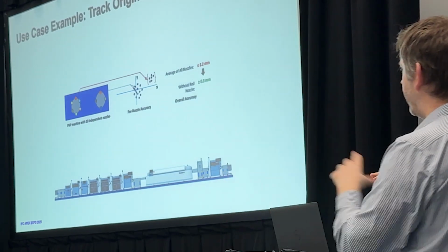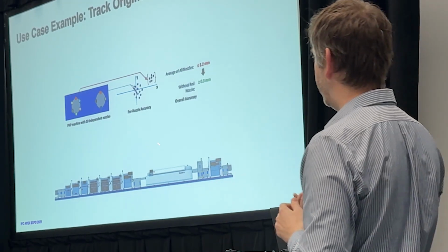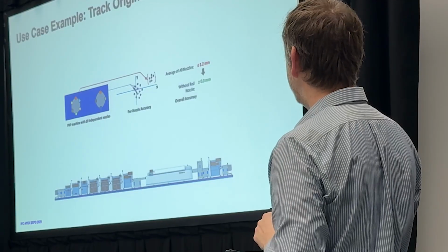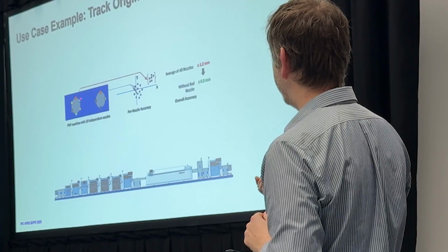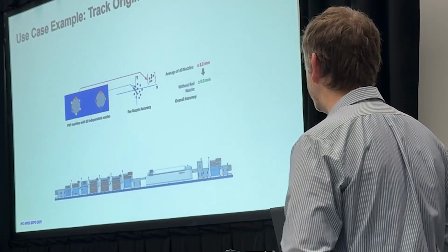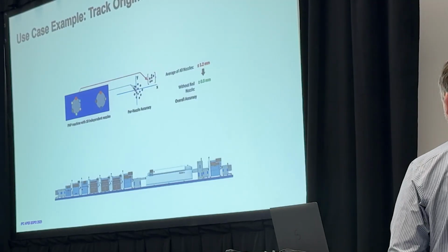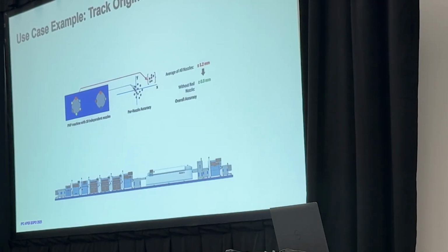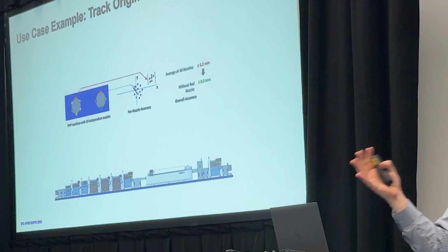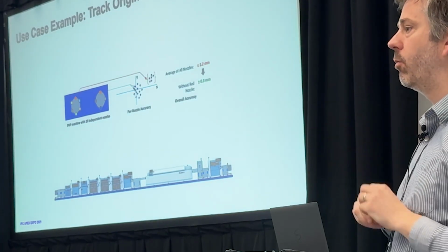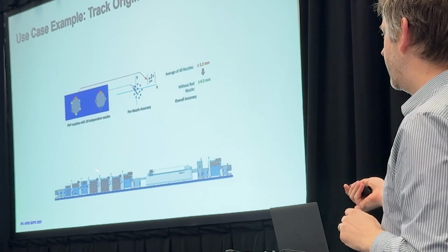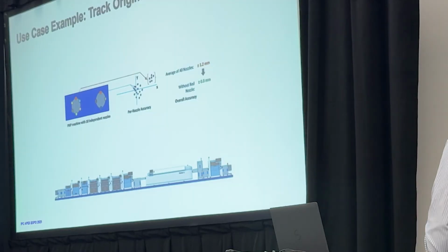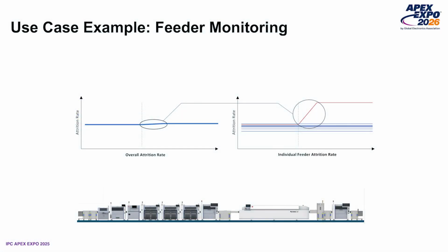And now with that data linked together and annotated, collected on every single placement, I can say, well, if I go and fix up this one nozzle, I can take my repeatability down to say like 0.3 millimeters on this placement. And this is just something that requires putting data together from two machines and then looking at what you can now say, given what the pick and place knows and what the AOI knows. A similar example is feeders.